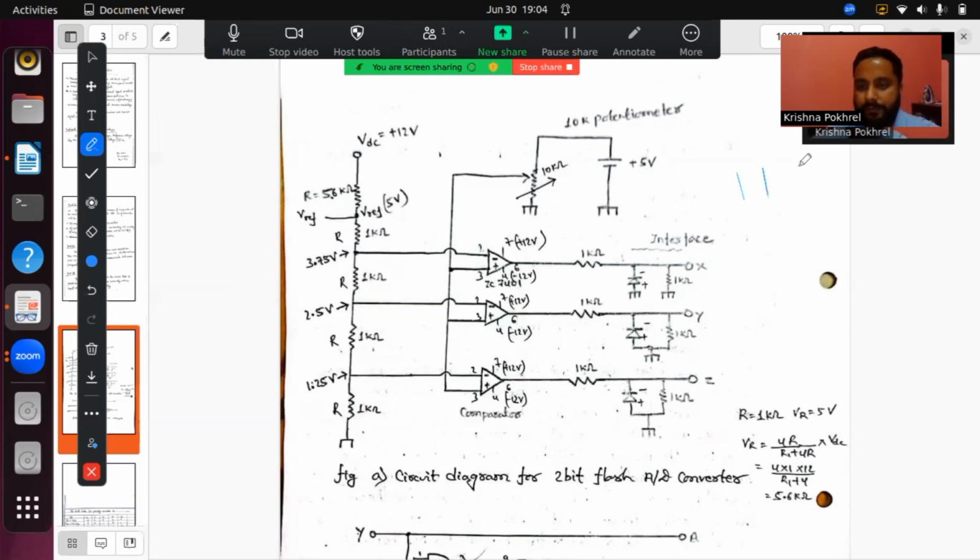In a potentiometer, we have 3 terminals. We will connect the third terminal to ground, and we'll connect the first terminal to 5 volt, and the middle one goes to this overall circuit. This is the circuit connection of this potentiometer, and we'll change it and set up the voltage. This voltage name will be VA.